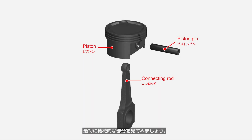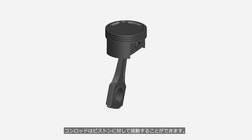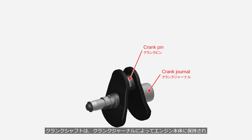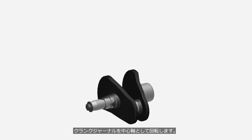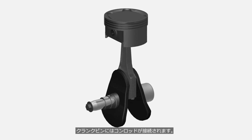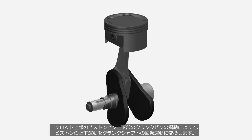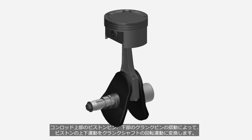First, we will look at the mechanical parts. The piston and connecting rod are connected by inserting a piston pin, allowing the connecting rod to pivot relative to the piston. The crankshaft is supported by the engine block via the crank journals, and rotates around the central axis of the crank journals. The connecting rod is attached to the crank pin. The sliding motion of the piston pin at the top of the connecting rod, and the crank pin at the bottom, converts the piston's up and down movement into the rotational motion of the crankshaft.